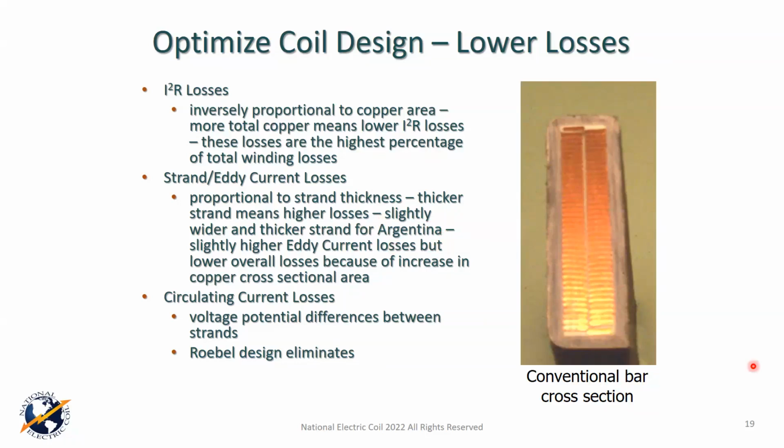Adrian asked the question, why 6-phase connections on a stator when you only have 3 phases? There are a lot of different configurations, but the reason you have 2 at each position is you have a main and a neutral. If you're asking why you have 6 positions when you only have 3 phases, it's basically a 2Y connection, so you have 2 groups of 3 phases that make that up, I believe is the right answer, Adrian. But if you want to contact me later and you have another specific question, maybe I can get into what you're seeing and help you a little better with that one.